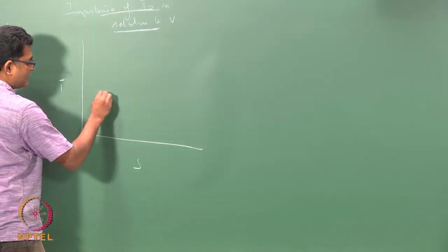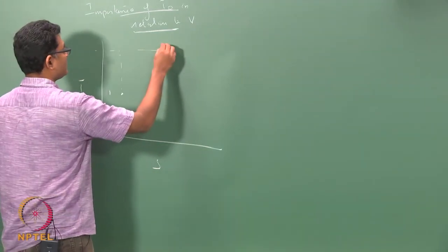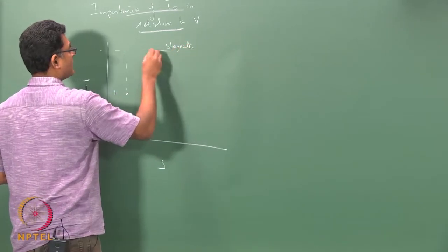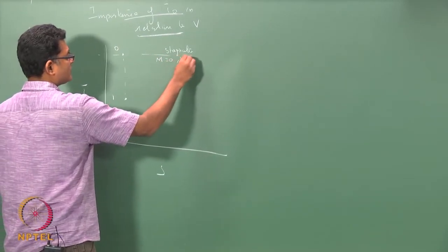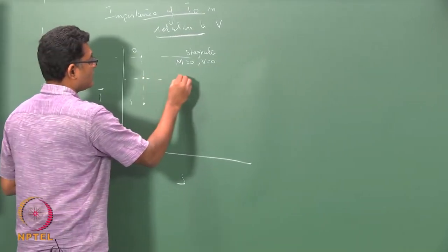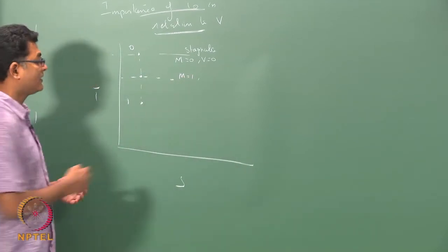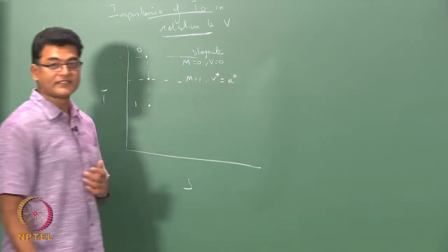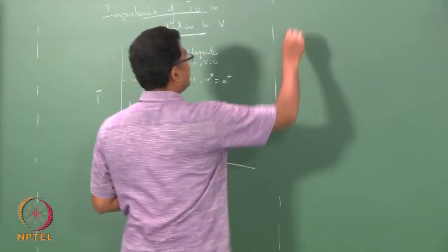So, I had state 1, I isentropically made the velocity to be 0 at the stagnation point. So, that is a 0 condition where my m is 0 or the velocity is 0. Okay. We have also seen how the m equals 1 condition produces a new reference quantity, which we call as V star, which is equal to our velocity of sound A star at the same condition. And we look at the equations.